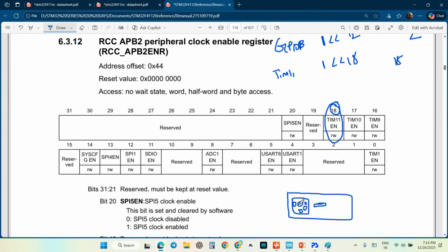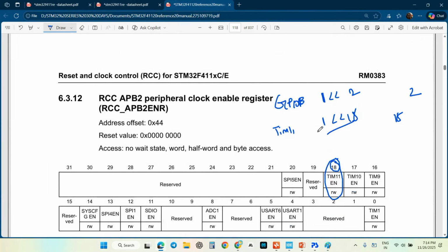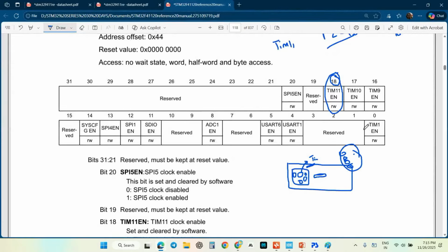So these are the registers. If you are taking a timer, it has different registers: status register, control registers and all. Inside this, you have to set specific bits. If you want to enable the timer inside this microcontroller, you have to enable this one. For that we are just shifting and enabling the one. If you want to use the peripherals inside the registers, you are going to set the specific one. After that we will move to that work.